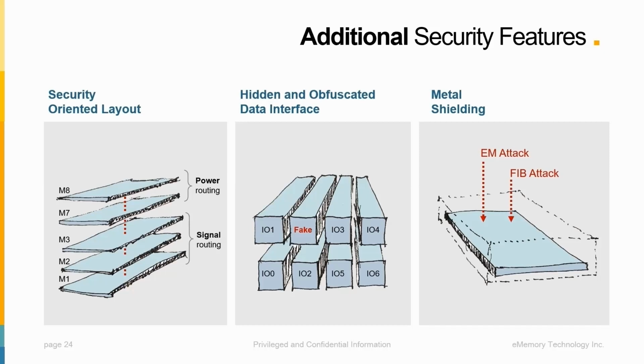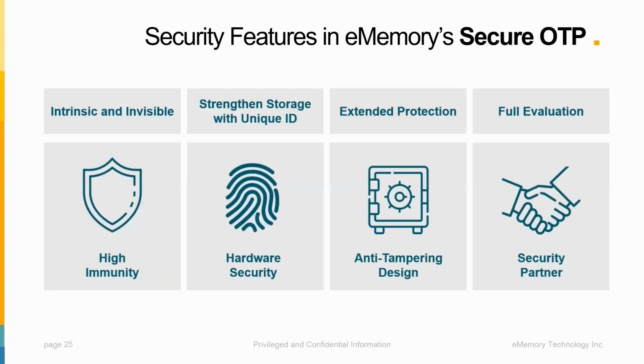So to answer the need for secure boot, as well as better and safer digital key generation and storage, Secure OTP, a PUF-embedded NVM solution, is introduced. The Secure OTP comprises NeoPUF for device unique key generating and NeoFuse for reliable secure OTP storage. This solution offers intrinsic high security storage, as NeoFuse storage cannot be visualized externally. In the meantime, the Secure OTP also offers a unique fingerprint ID for every device, which can be used to increase hardware security, such as device unique data address scrambling.